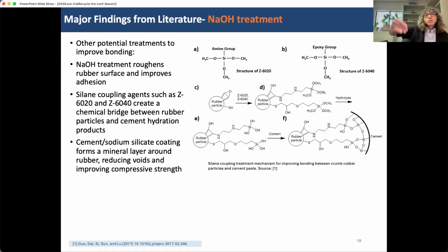So the reason I introduce these types of treatments is that ultimately our goal is that if we're putting those 3 sacks of cement, which does have a relatively high environmental impact, global warming potential, we don't want to compromise the amount of strength that comes with the material.